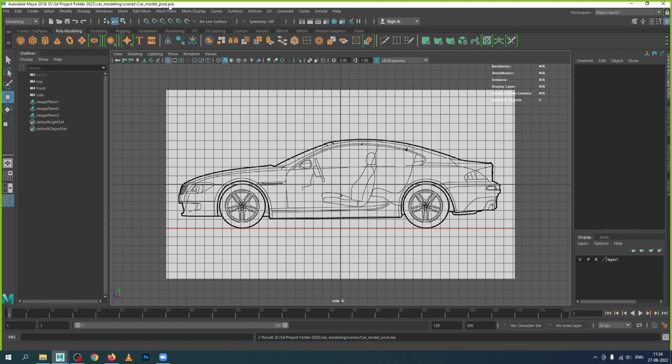Final stage, when complete model is ready for the day, that time store this as Maya ASCII file. Otherwise you have to travel from one file to another file, one file to another file. You will get confused. That's why that also I am clearing. Initially all stages should be saved in MB file. Only one stage, final stage of the day, that has to be stored in Maya ASCII and Maya binary file. Clear?